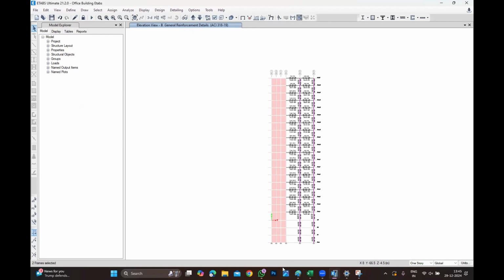In order to design the wall in ETABS, you need to give some kind of ID name, pier ID. Then ETABS will understand you're instructing the command to design the wall, or else ETABS doesn't understand. This is only a matter of ETABS, not in terms of technicality. Only for ETABS, to design the wall, you need to give some ID name.